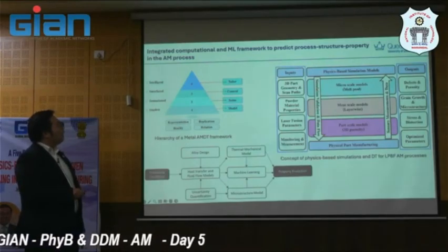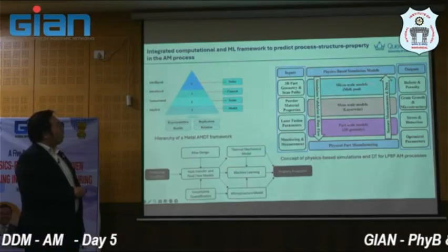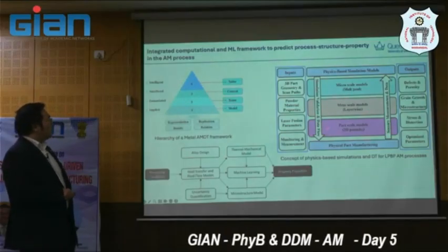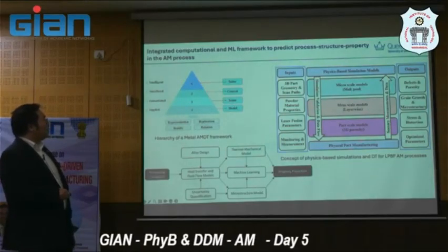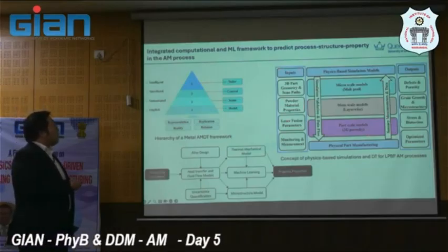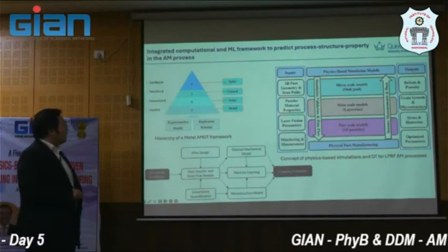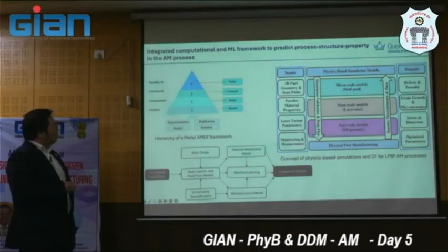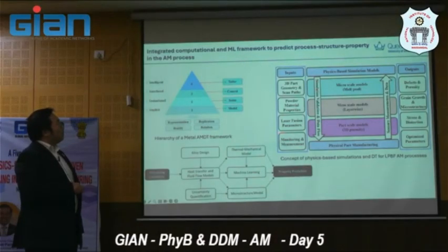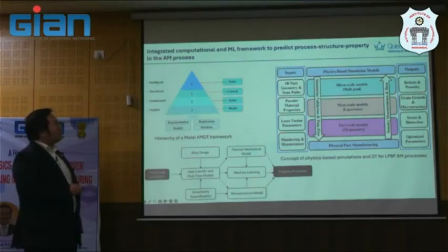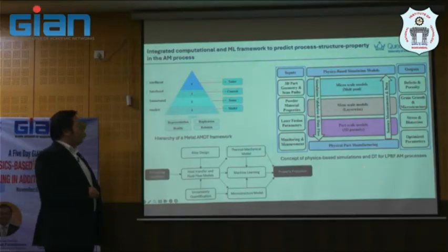Across the length scale, as I said, this is 3D printing now in the micro length scale, in the melt-pool, meso, in the layer-wise, and then 3D printing level in the part or defect, something like that. So this may be an input: the geometry of the 3D printed part, powder material property, and then laser fusion parameter, monitoring and measurement here. And output will be defect content that we said before, grains, growth, and microstructure, stress and strain, distribution, distortion. And we want the output of optimized parameter.